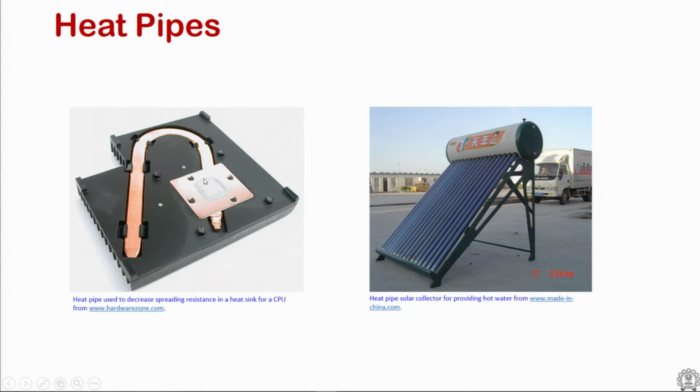structure, where this is the so called thermal interface material that would make contact with the electronic device, and this is the heat pipe. So, the heat is carried from this location to this location, and the heat sink mounted here, you can see some fins here, would dissipate. So, this is the advantage of a heat sink, to carry heat from here and take it to a location where it can be dissipated much more effectively or provide a larger area for heat spreading.